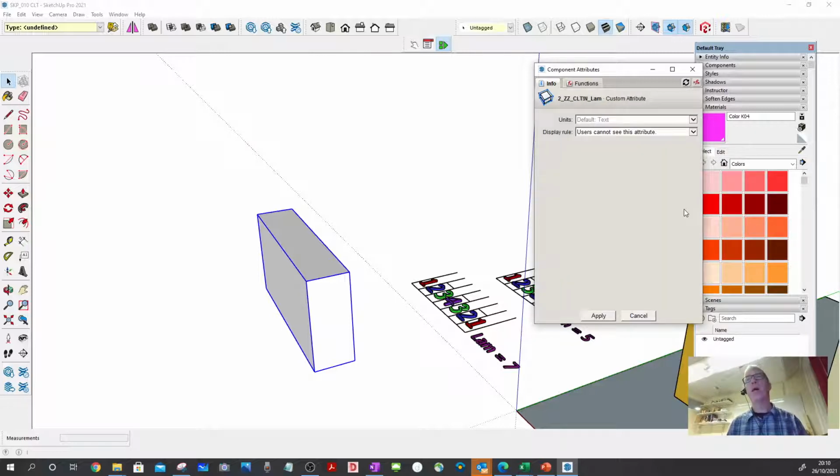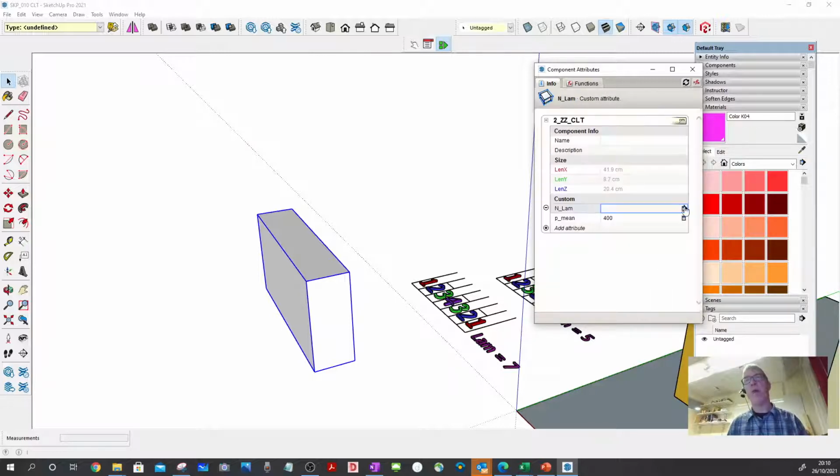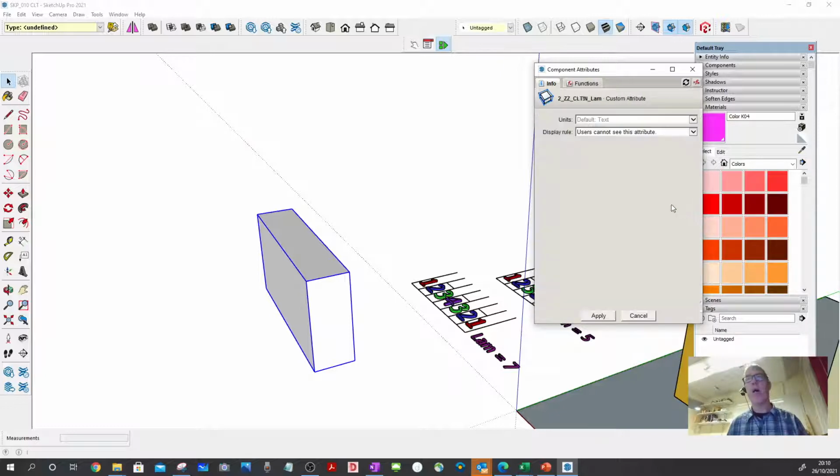In here, I'll do that one more time. We'll press this icon, and that brings a control function up. The display rule would be that the user can select from a list. For the units, let's have a decimal number, and let's have the options 3, 5, and 7. And that's 3, 5, 7 for both the list option and the value.